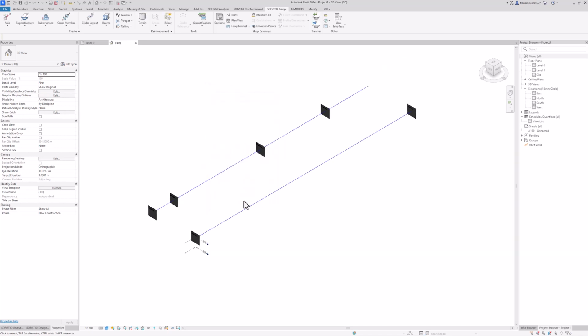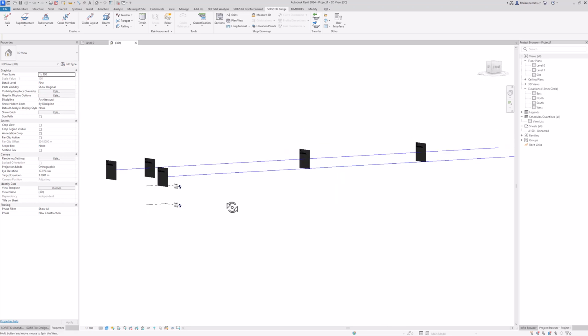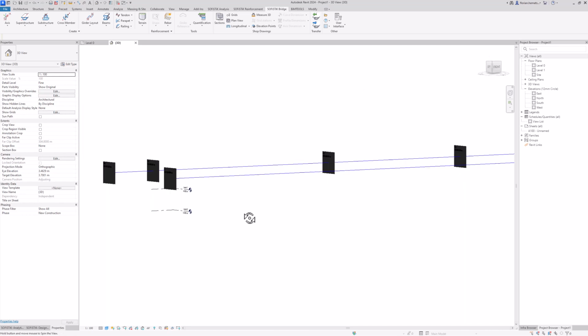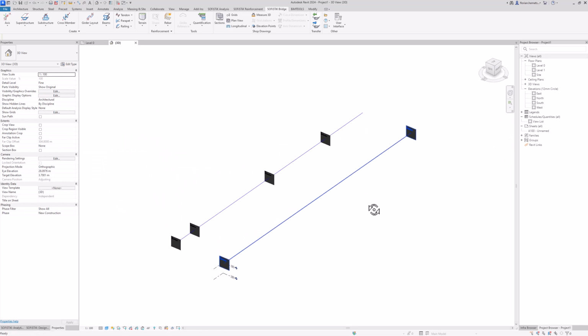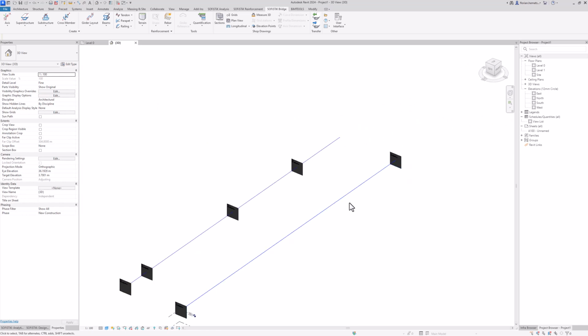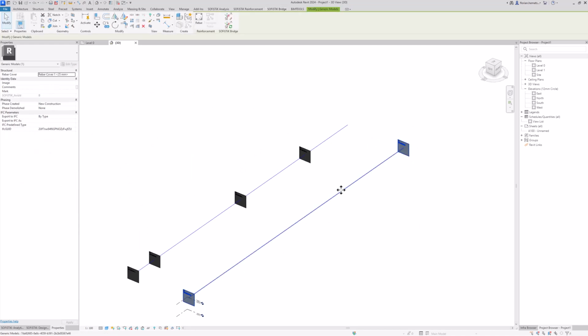Once I click on OK, the new axis is created according to the input that we gave to this input dialog. You can also see that this external axis is aligned to 6 meters and it already has a length of 100 meters. The only thing that is missing compared to our manually created axis is the placement information.